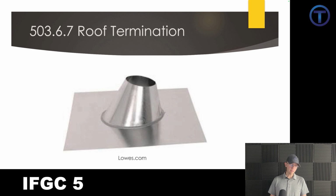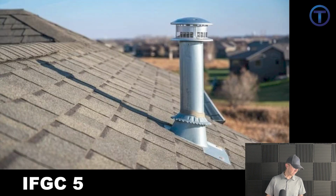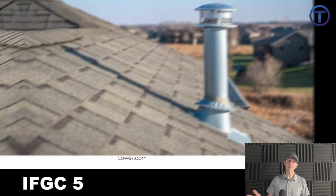503.6.7 talks about the roof termination and basically states that the gas vent shall extend through the roof flashing, roof jacket, or roof thimble and terminate within a listed cap or a listed roof assembly. So we don't just leave that pipe wide open. It's got to be flashed. It's got to be sealed so that weather can't follow that pipe down and destroy anything down inside the house.